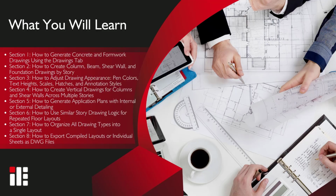In this video, you'll learn how to generate and organize all your structural drawings in ideCAD Structural. You'll start by creating formwork and reinforcement concrete drawings directly from the Drawings tab. You'll see how to customize pen colors, hatching, text sizes, and scales to match your documentation needs. Then, we'll generate detailed application and vertical drawings for columns, shear walls, beams, and foundations across multiple stories.